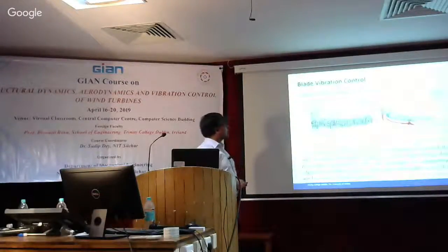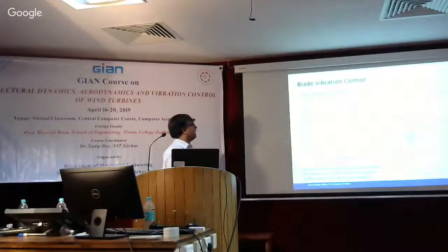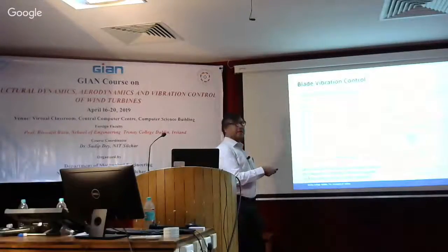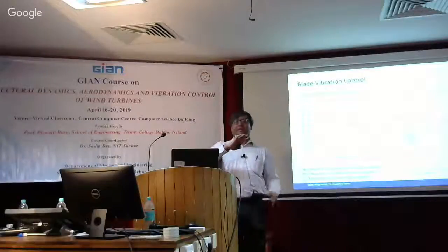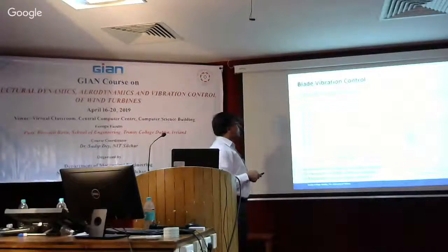And these are the results. Obviously the control is quite impressive, as you can see, when you can control the vibration well with that tendon. And with the two-control strategy, we looked at both the out of plane and in plane blade response. This is a case where we looked at the pre-twist of the blade, and the coupling between in plane and out of plane forces and vibration. Obviously, you can see that if we have, say for example, a pitch angle of 6 degrees, our out of plane response is approximately reduced by 50% when we have an active tendon force.